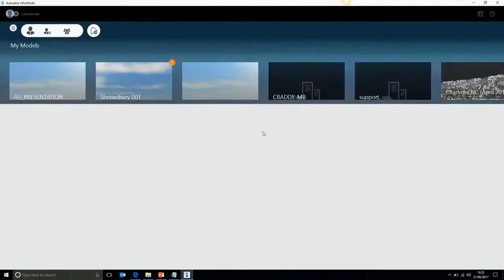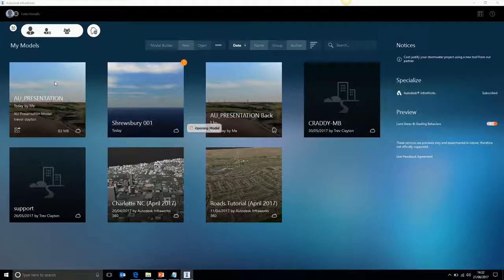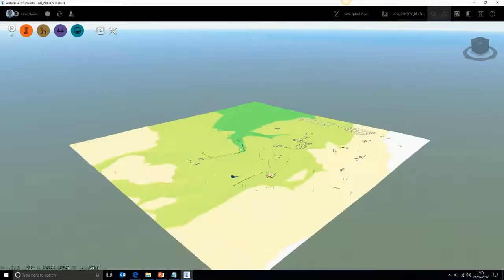Once I've got it back to a component road, then, as I was saying, it then gives me functionality within the InfraWorks software to actually then adjust the alignment. It allows me to drag and connect it to another road. Doing so within the software, as you may know, will automatically create the junctions, again, in accordance with the DMRB that we've actually got preloaded. Let's just jump into there.